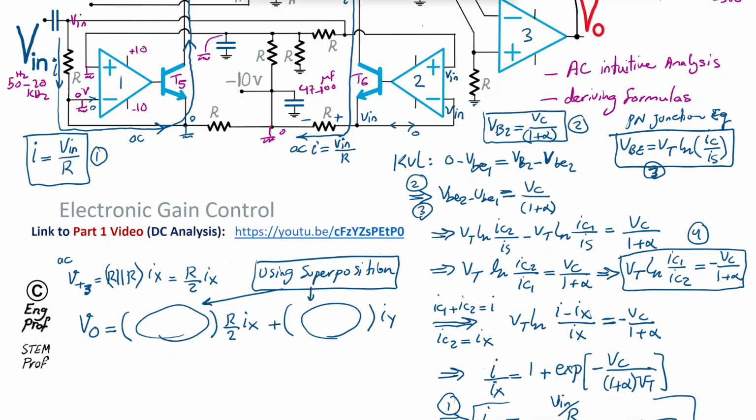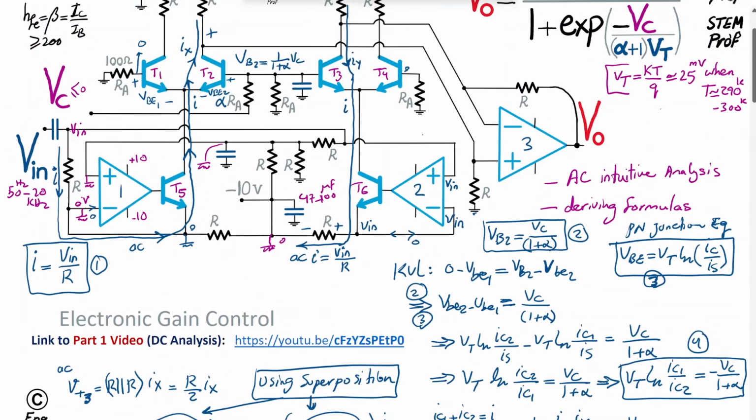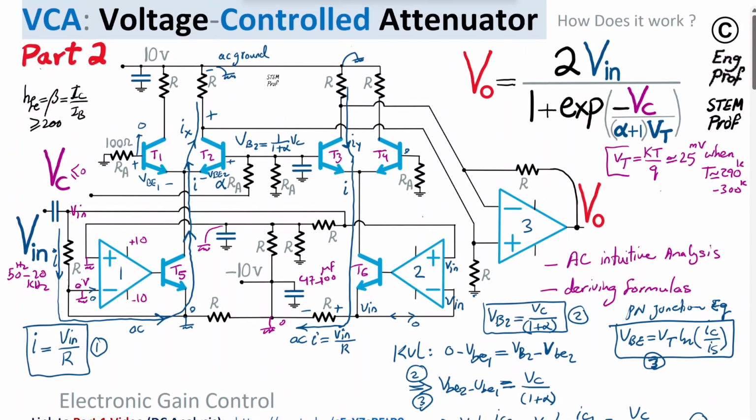I'm going to make the assumption that Iy is 0, not there, and figure out the contribution of Ix, and for Iy and its coefficient, I'm going to make the assumption that Ix is 0, not there, so that I find them. First, for Ix and its contribution, assume Iy is not there, so as if Iy is 0, which means, effectively, this is open.